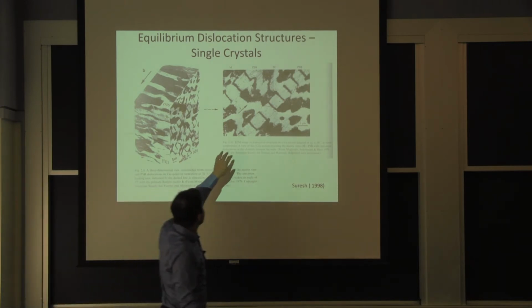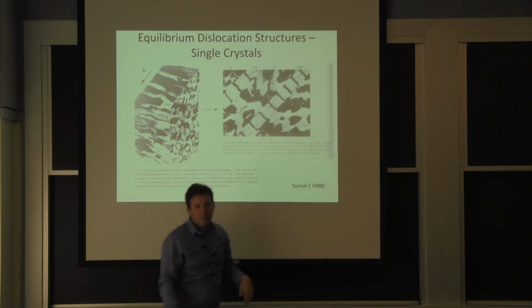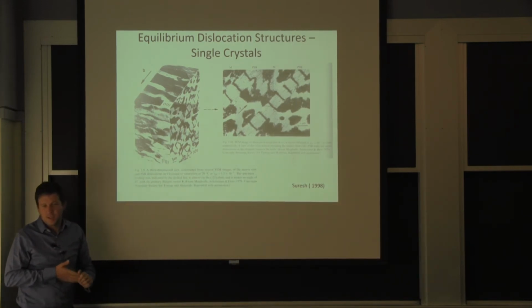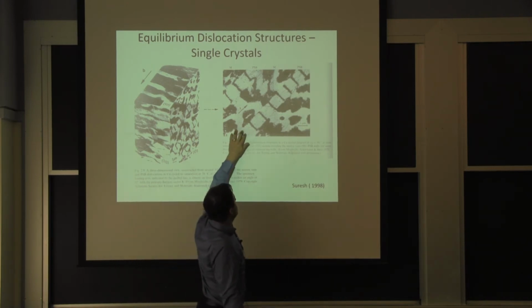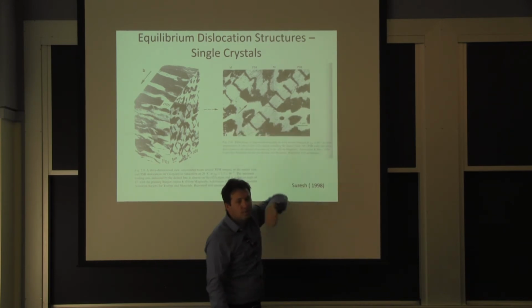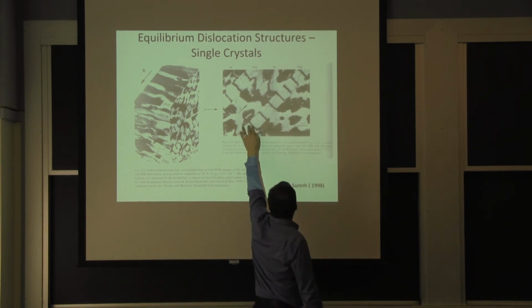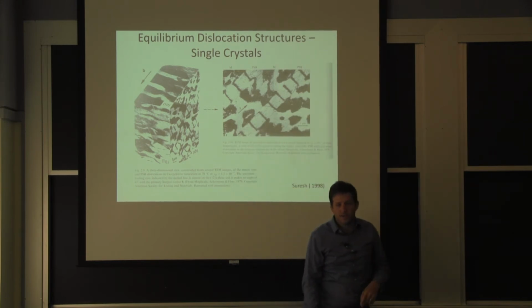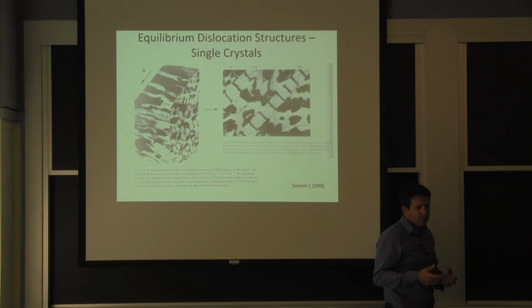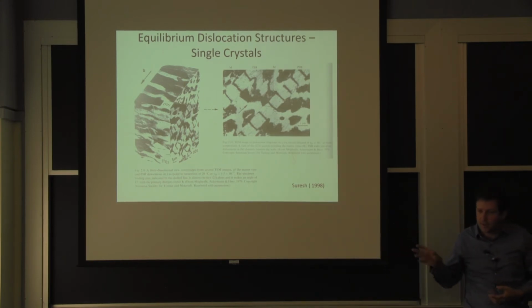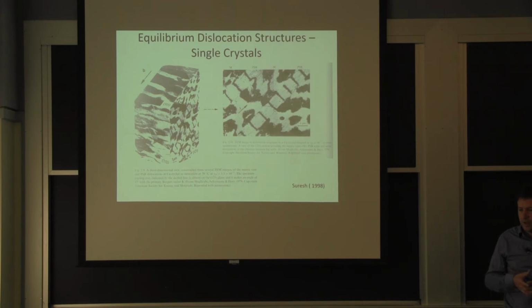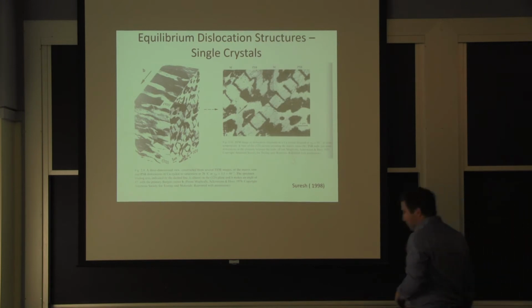So you have that ladder, for example, that got a lot of people excited the first time they saw it under the microscope. It's a zone in the crystal that has very little density of dislocations, and all the dislocations are stacked up in those planes. So when I come again to make a deformation, all I do is take some dislocations somewhere and have them travel to the other side. I form that stable structure. Not necessarily this one. This one will come and disappear, but there are dislocation structures that essentially persist if I keep deforming. I should show you that because that's important.